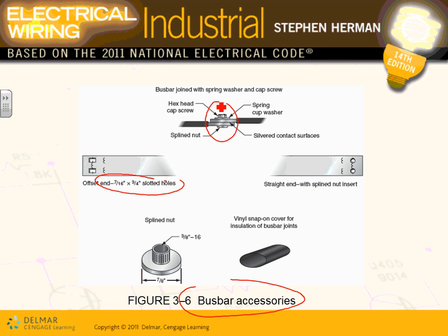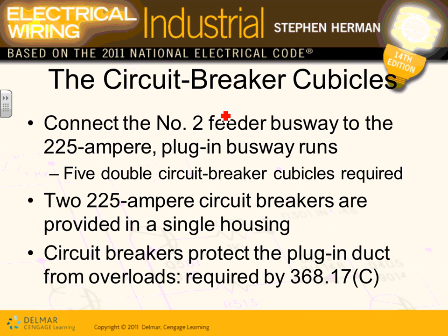I don't know if you guys remember, I think his name is Kent, yesterday. He was talking about how every 3 years they shut down and go torque all these bolts over here. They torque them and make sure they're tight enough. Otherwise, they will arc. So busways, guys, like panels, need a lot of maintenance. Every year you have to do thermal imaging for them, like you do with all the other equipment. And at intervals of 3 to 4 years, you literally go and torque and tighten all these so they don't arc. A lot of hardware.